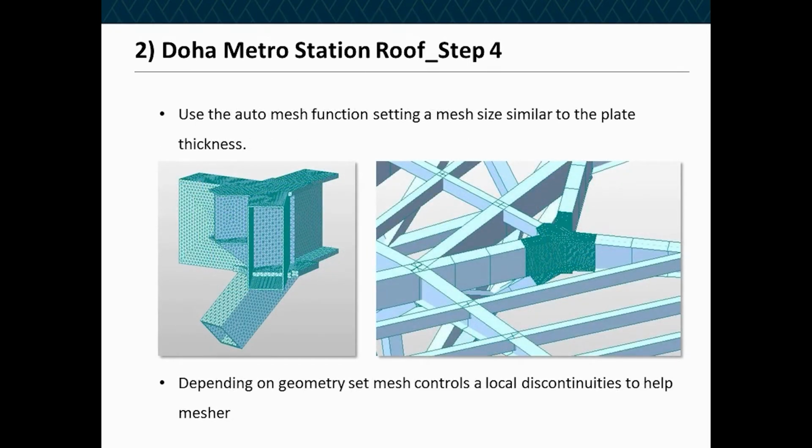When you have a solid that works, and by works I mean you want to avoid, if your fusing and your subtractions don't work, then you'll have something called a non-manifold volume. And the program will tell you that you've got that, and then you just undo and you work out what it was that wasn't quite right.